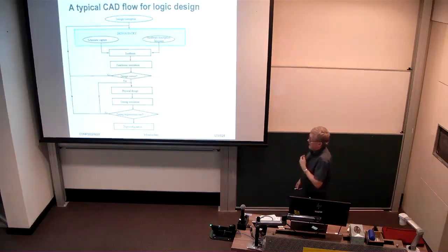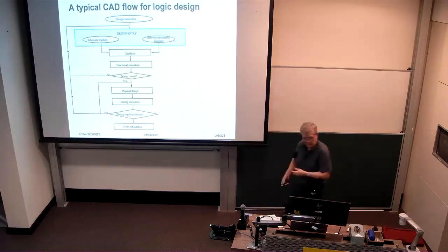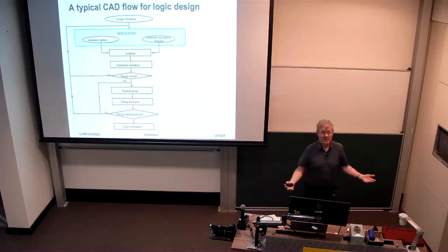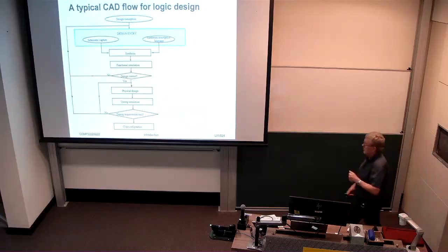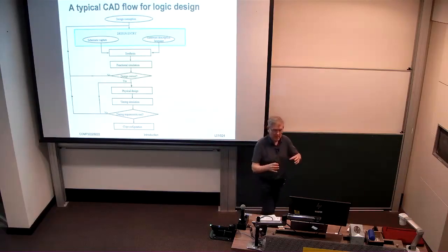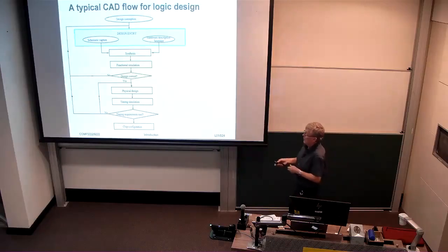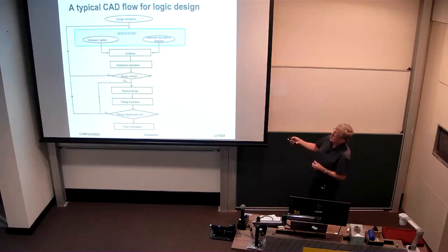Okay. Now, I told you about those configuration files. How are they produced? So this is a schematic, it looks sort of dated, but it's accurate. This is how things work. Generally, you have some idea for a design. You start with some requirements, and then you need to specify how you are going to implement that design. We've already talked a little bit about the two alternatives: either a schematic capture where you draw the diagram by hand or using tools and input it into the rest of the flow, or you use a hardware description language. And that's the route that we're going to take.